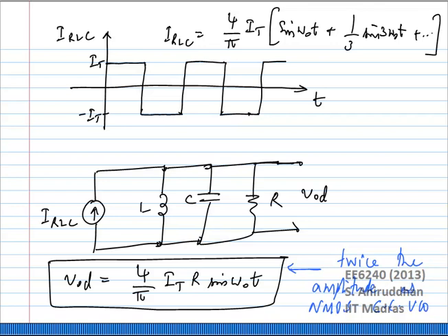Okay, which is why when we started off, I already told you there may be some VCOs which give you sinusoids, some VCOs which give you square waves. We are really not interested in directly distinguishing between the two. In many cases, even when you have a sinusoidal oscillator, you quite often convert it to a square wave and then use it. Even when you embed it inside a PLL, the PLL is interested only in the phase of the signal. It is not interested in the amplitude of the signal. Okay? So at the end of the day, we are interested in the phase of the signal. And if these zero crossings of the VCO signal have imperfections, we are really, really worried about them. Okay?